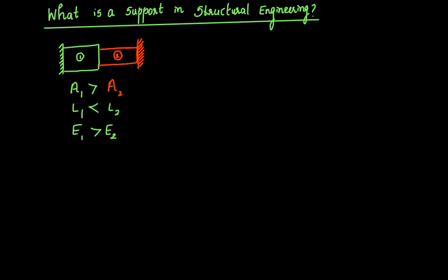We know what is the formula for stiffness in the case of a bar. Stiffness is given by the expression AE divided by L. It all comes from stiffness. The general definition for stiffness is the amount of force that you have to apply to stretch a particular component, you may want to consider a spring, by a certain magnitude. So that is what is called stiffness.